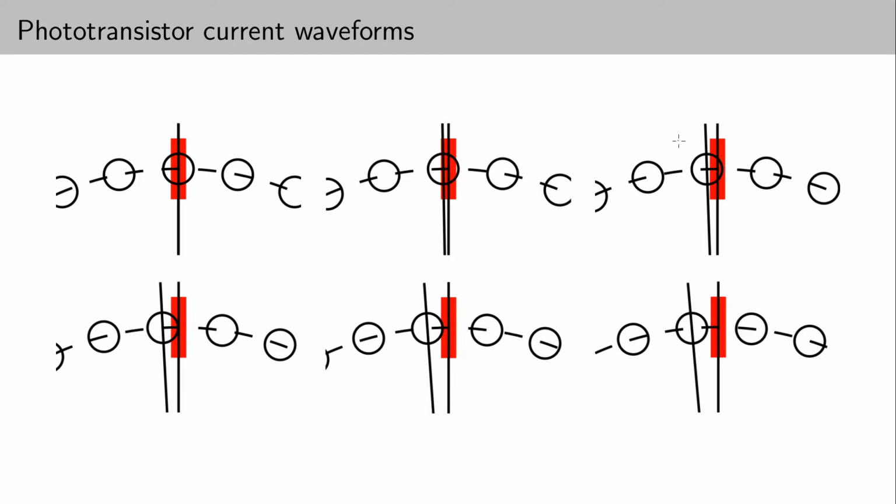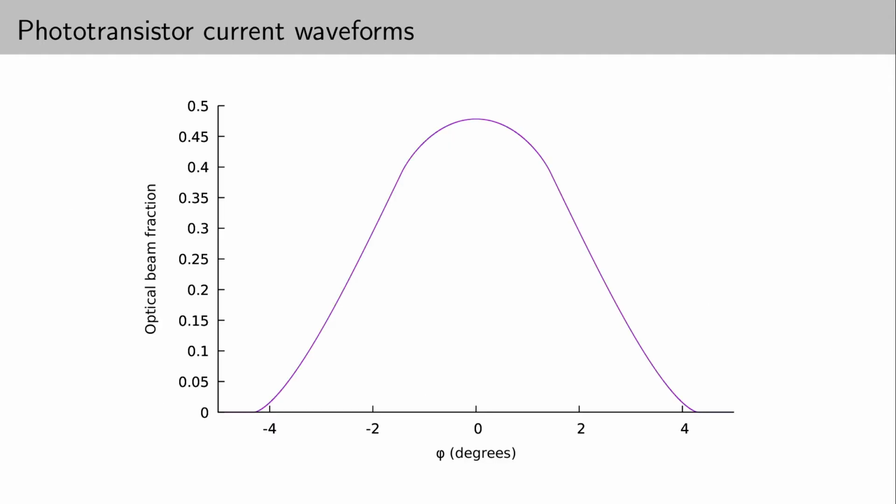So as the hole moves on, this overlap area gets smaller, and eventually the hole doesn't overlap with the optical aperture at all anymore. So the radiation from the infrared LED is completely occluded, and none gets through to the phototransistor.